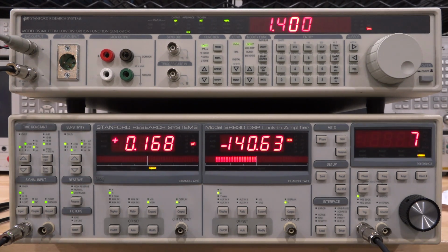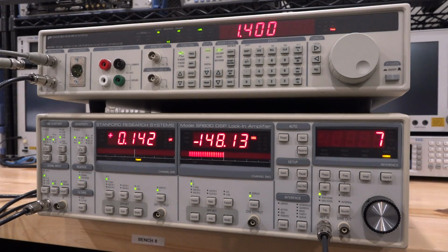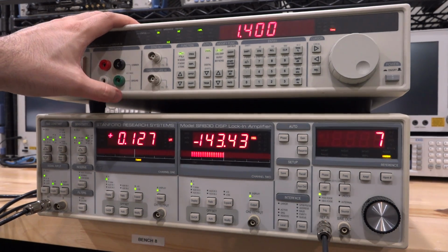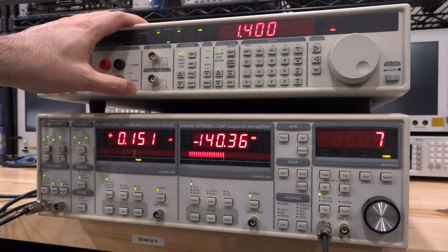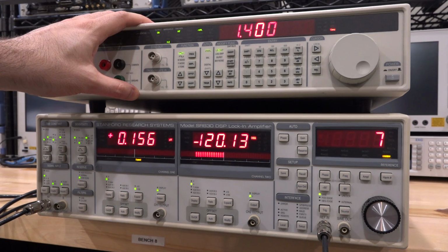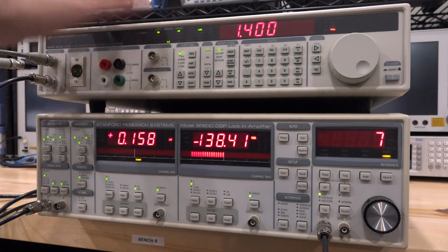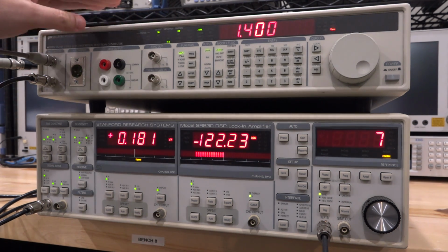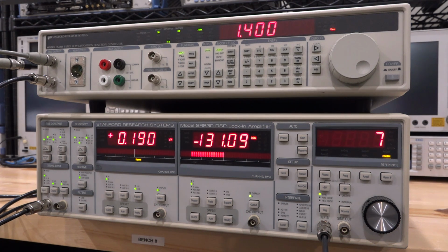So we basically made this measurement using a lock-in amplifier, which is a little bit unconventional. Now there are a lot more verification steps to really make sure this is working up to the factory spec, but given that it works in the THD, which is one of the toughest, I'm fairly confident that probably the whole thing still works. I'll do a couple of other tests on it just to make sure, but I think we can add this to the lab for future uses. And when I do get that dynamic signal analyzer, we can see if we can measure it raw on that analyzer, because that analyzer itself is supposed to have better than 110 dB of THD.